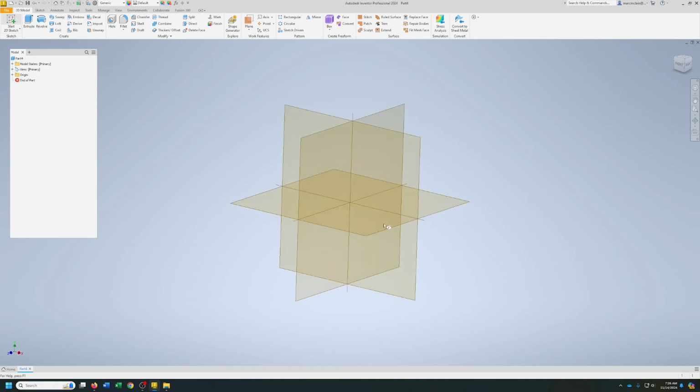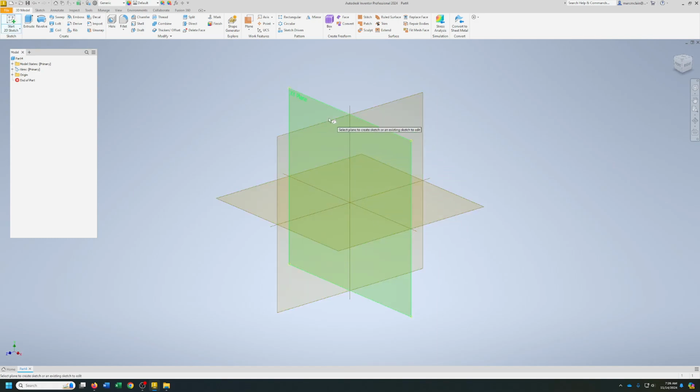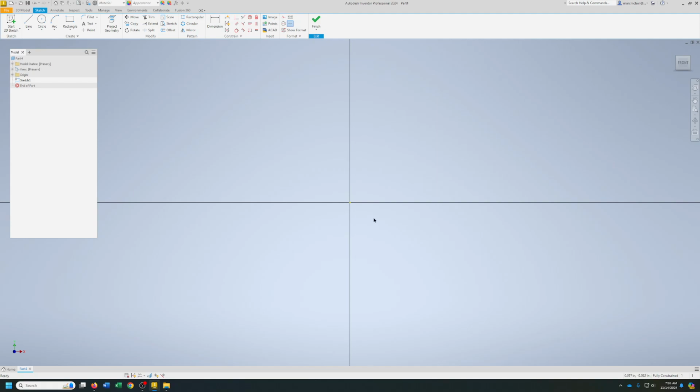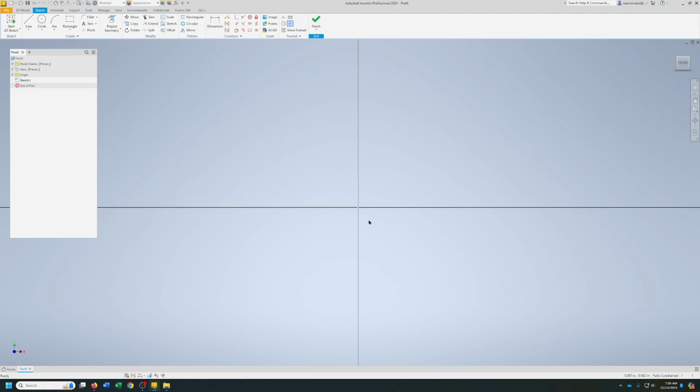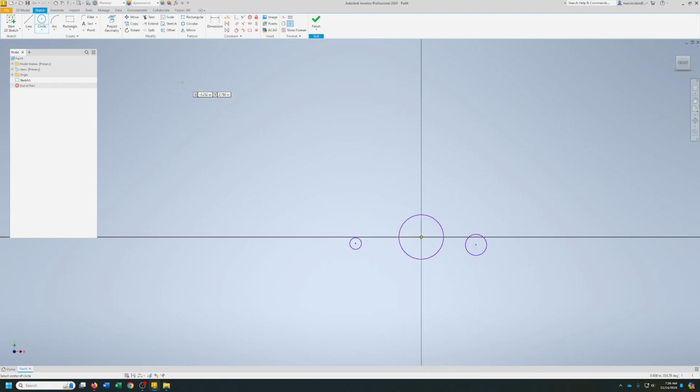And we'll start our 2D sketch. Now, pick that front face again. I'm going to start in the middle of this thing with that hole that's right in the center of it. It's number 3, positioning stop. Okay? So start with a circle. And it doesn't matter what the size is. We got a couple more circles over here and over here. And then I'll just sketch this. Whoop. Helps if you hit line. There we go. I'll just sketch this.